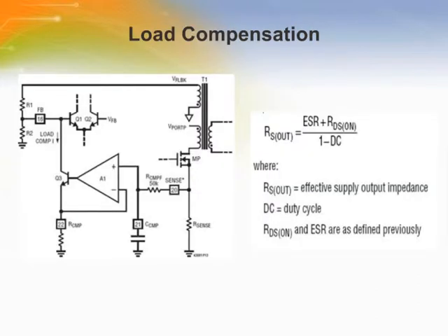The LTC4268-1 uses the flyback pulse to obtain information about the isolated output voltage. An error source is caused by transformer secondary current flow through the synchronous MOSFET RDS(on) and real-life non-zero impedance of the transformer secondary and output capacitor. The secondary current only flows during the off portion of the duty cycle.